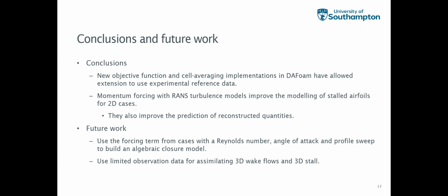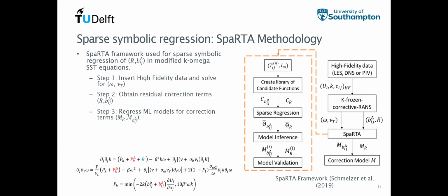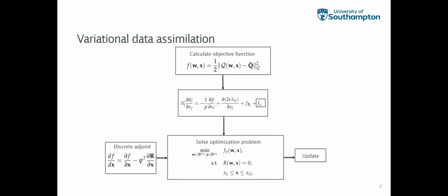Yeah, please go ahead. So the correction field in your work was a source term in the momentum equation? That is right, yeah. So you weren't using any turbulence model, just the momentum equations, right? So a turbulence model is in fact used. Let me just go back to the equation, and perhaps we can quickly take a look. Yeah, so here, if you see here, let me just get a laser pointer. So this correction term that you see here is the one that we're optimizing, but that's a corrective forcing. But there's also a Reynolds forcing here, for which we use a turbulence model.